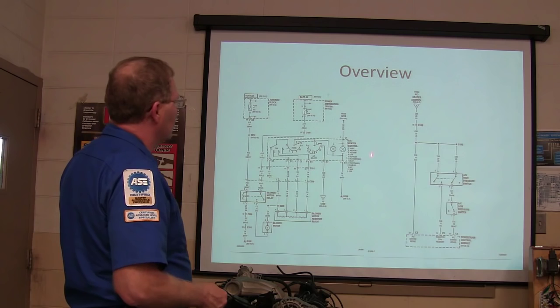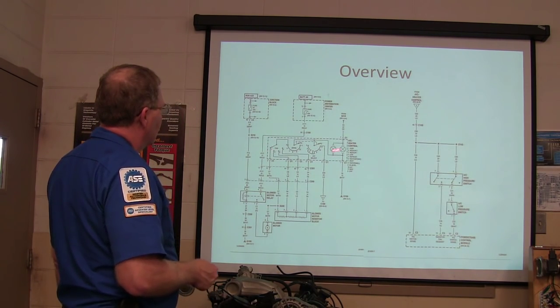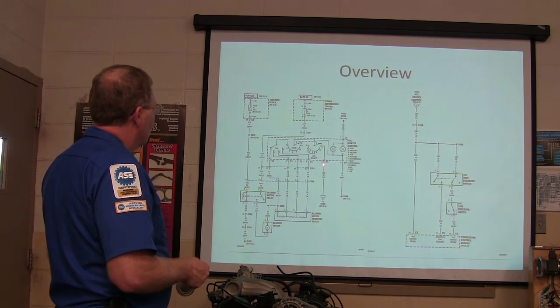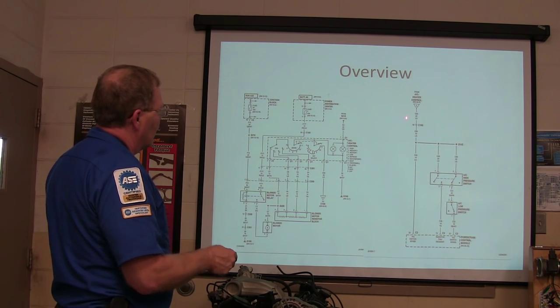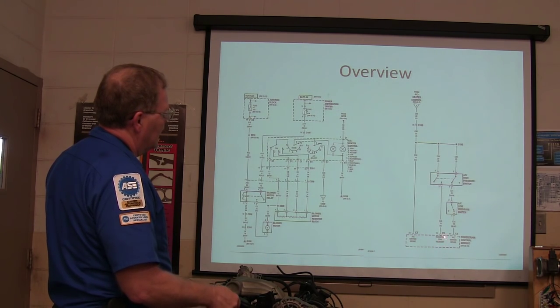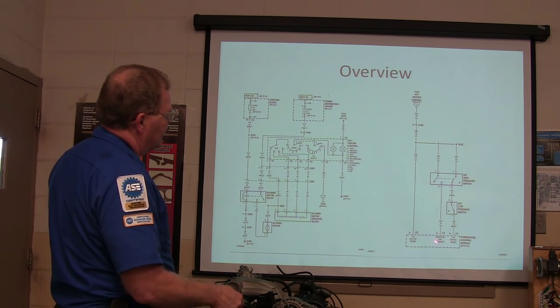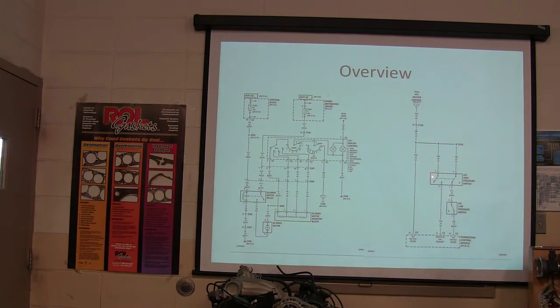All right, this is an overview of the way the Jeep is wired up. Basically, you've got your heater switches right here, and see A right here. Whenever you turn on the air conditioning, you're basically putting power out over here to the AC switch sense on the powertrain control module, and then you've got these two separate leads coming up here. Right here you've got an AC high pressure switch, there's two switches in one, and down here you basically got a 12-volt feed that will not burn a test light.